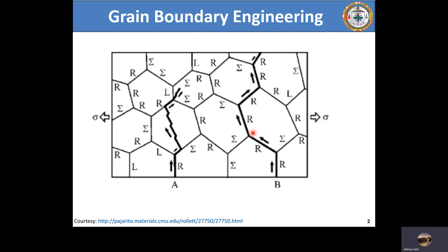This is a very simple way of illustrating why we need to achieve grain boundary engineered microstructures. First of all, for the case of metallic materials mainly subjected to structural applications, we need to have a huge crack resistance for the material. So that's the first reason, something which definitely comes to your mind when you see this particular schematic. Any kind of crack, it can be tensile crack, it can be fatigue crack, and so on.